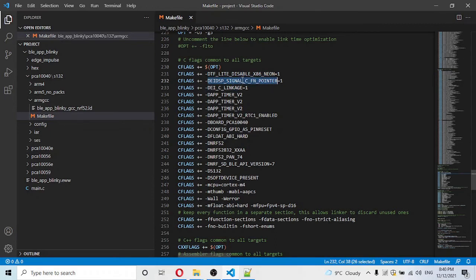What they do is the following. The library that you exported from the Edge Impulse website is a C++ library. By enabling these two flags, you compile the Edge Impulse API as C. In the nRF5 SDK, we usually have C code, not C++ code. So it is better for us to work with C files. By enabling this flag, you solve many of the integration problems. If you do not do this, you may run into problems.